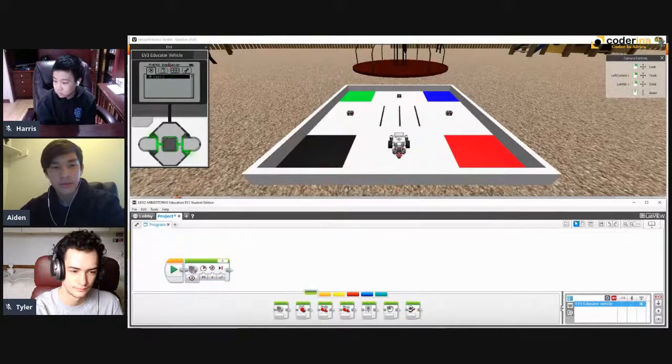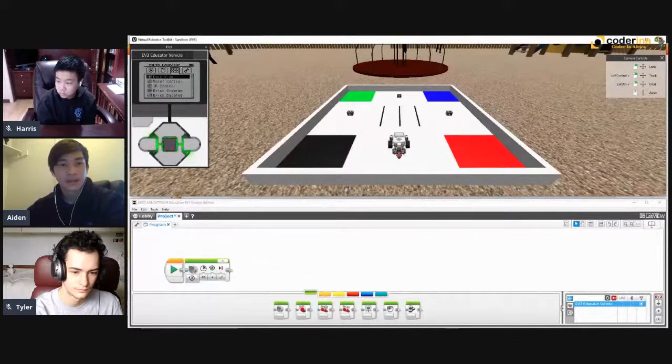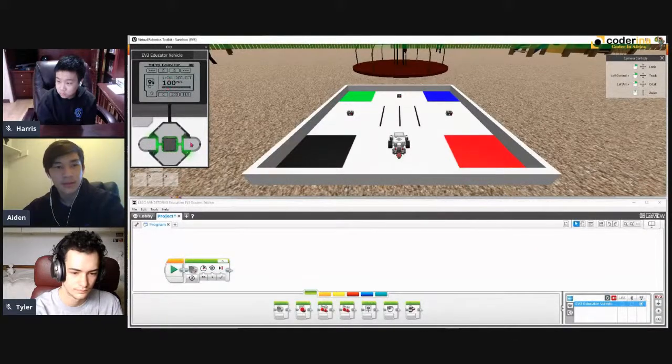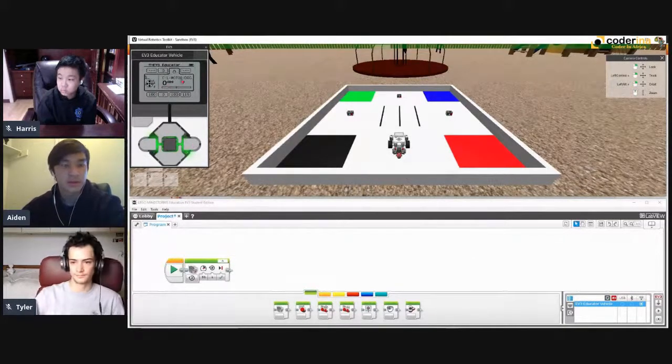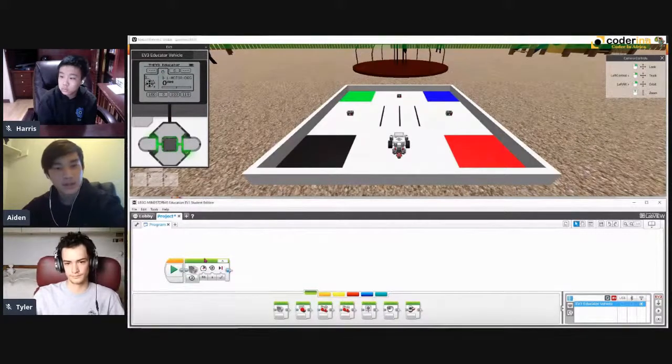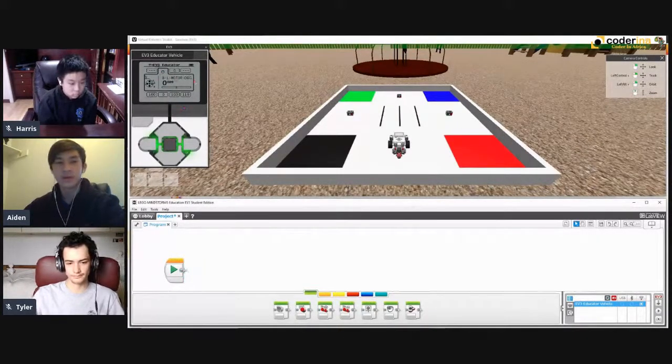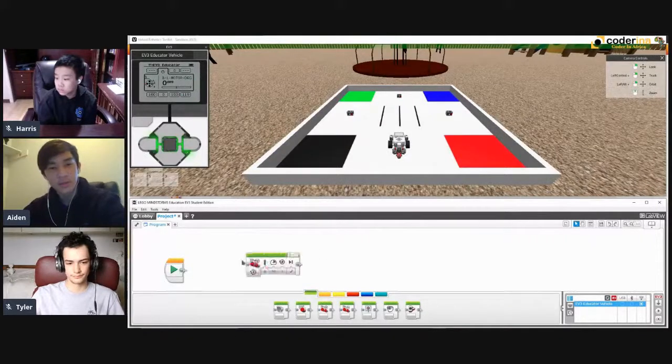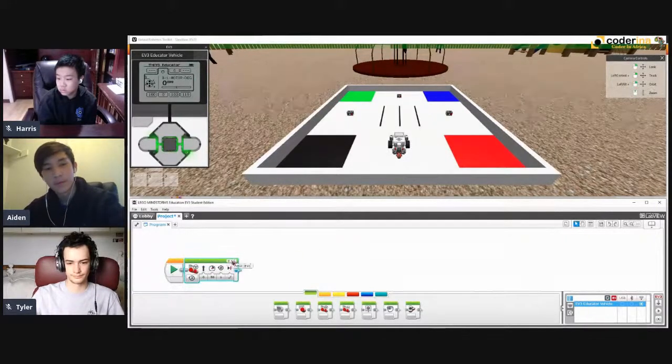But as you can see on our robot, we actually don't have a medium motor. And if you want to see that, you can go to this tab here. And then in order to go there, you can just use the pad at the bottom and click on port view. And then here we have all of our sensors. And you can see that the sensors are plugged into all the ports, but here we only have motors plugged into ports B and C. So if you build your custom robot and import it, then you'll be able to use the medium motors or any other motor that you would want. But on the default one, there's only B and C.